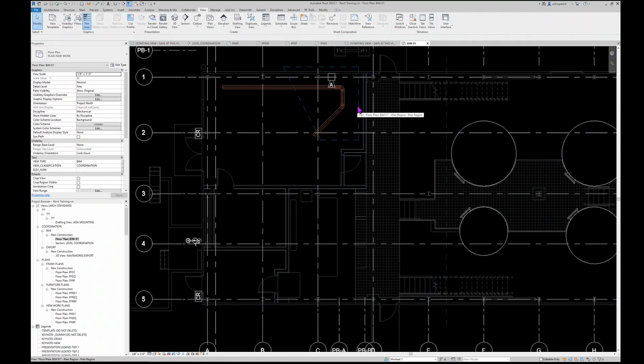We got pulled into a project about 2 months ago where it was easier going back and removing all the plan regions and starting from scratch on a view than trying to understand what they were trying to do originally and fixing them, because there were multiples in a view. And the thing also about plan regions, you can't put a plan region inside another plan region. Revit doesn't like that.